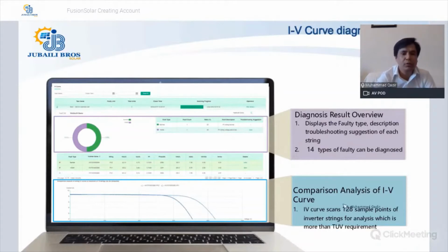At the bottom, you will also see a comparison analysis of the IV curve. The best way to get the information for the IV curve is by downloading the IV curve report. Now you will have the option of downloading a PDF report, which will give you the IV curve of each string, and below that you will see whether the string is healthy or not as a note.